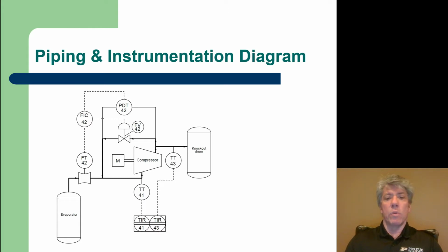And so what is the purpose of this FV42, for example? Well, FV42 is an unloading valve, essentially. If the compressor starts surging, it can damage the compressor, and so the point of FV42 is to open up and allow some of the output from the compressor to go back into the compressor. Now, this seems wasteful, but it's better than a messed up compressor. I believe what happens is when there's not a high enough mass flow rate, then the compressor can tend to surge, because it's kind of like a vacuum cleaner.